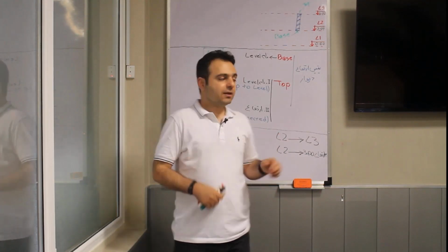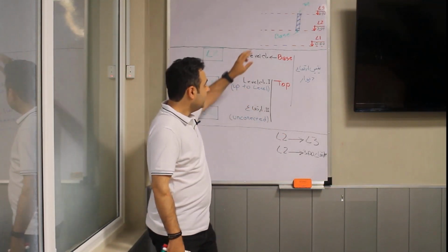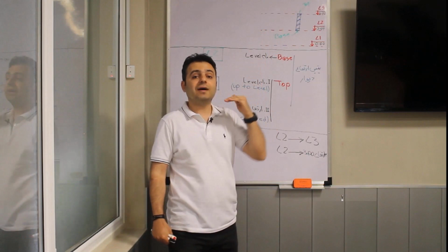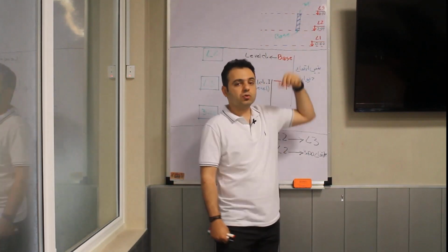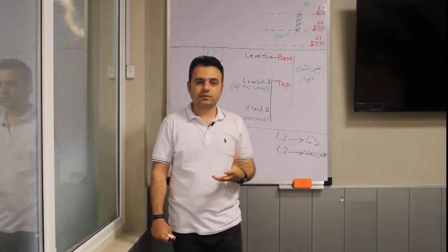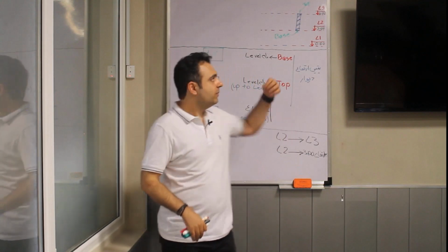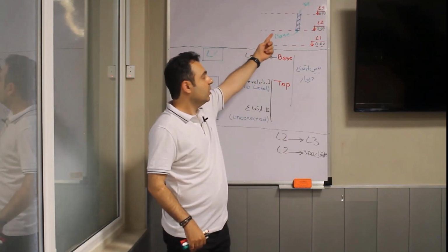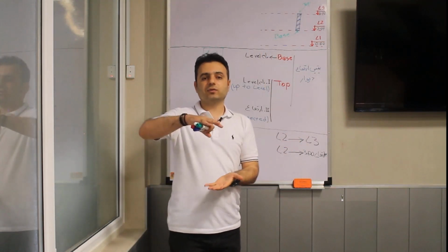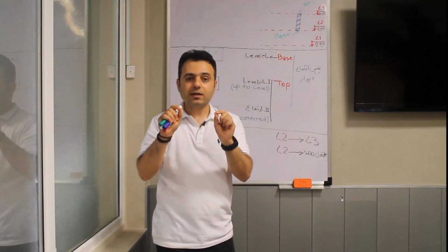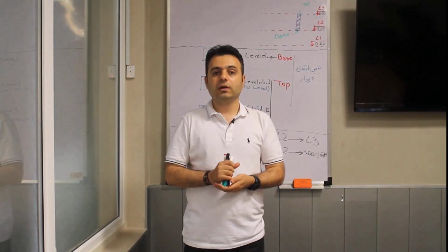But if you have already used the up to level method, that means you have connected the top of the walls to the levels. You just need to change this, for example, number 6 to 7. 1 meter is added to the floor and all the walls are increased too. Why? Because they're connected to the levels, so they change too. That means by changing one number, you can change all the walls.